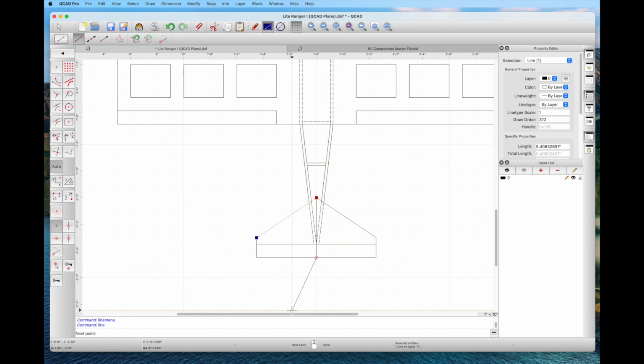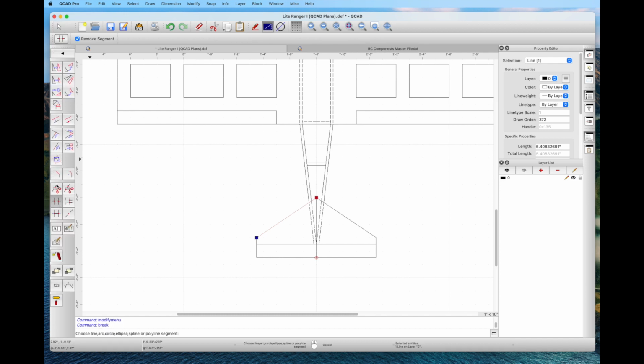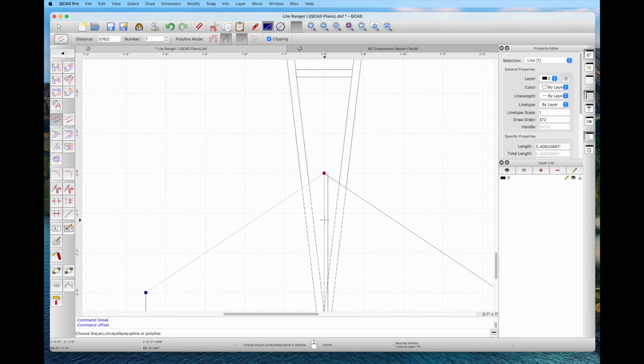We're going to draw the fin in right now, the vertical fin, so we'll use a center line. And notice with the parallel line tool, it's 3/16 inch wide foam board, so for the width of the parallel, we can type in a formula. In this case, 3/16 divided by 2, and that's half the width. So if we do that either side of the center line,